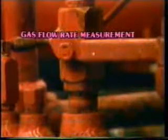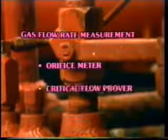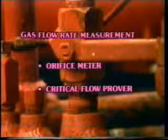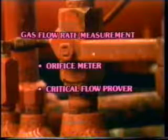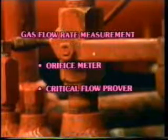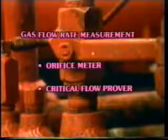Let us turn our attention now to measurement and sampling. We learned earlier that gas flow rate measurement may be accomplished through the use of an orifice meter or a critical flow prover. As turbine and displacement meters have become more accurate, they too have been incorporated into gas well testing. For example, Oklahoma now allows the use of gas turbine meters. Because of our earlier studies on gas flow measurement, we shall only make the comment that it is important that a proper orifice size selection be made prior to beginning the test.